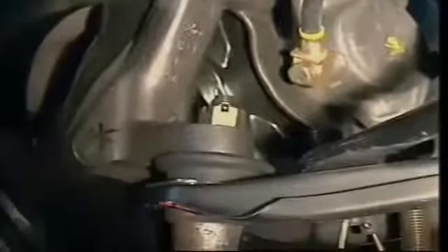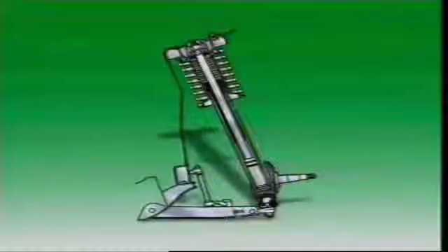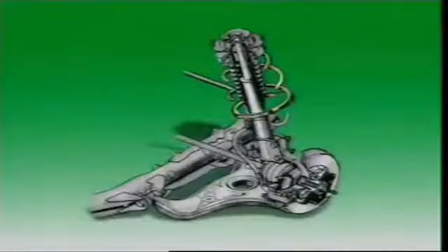The arms must be strong enough to withstand the forces due to normal operation, but light enough to minimize the vehicle's unsprung mass. The front suspension can have one or two control arms. Parallel link front suspensions have two control arms. Vehicles with strut-type front suspension have only one arm. It can be a wishbone shape with two fulcrum mounting points, or straight with single fulcrum.